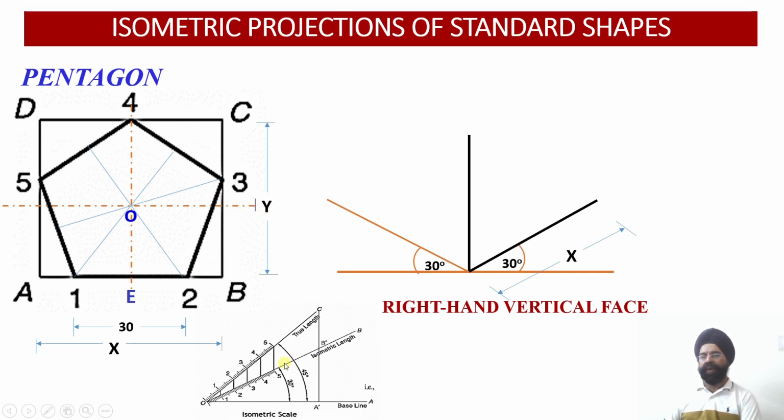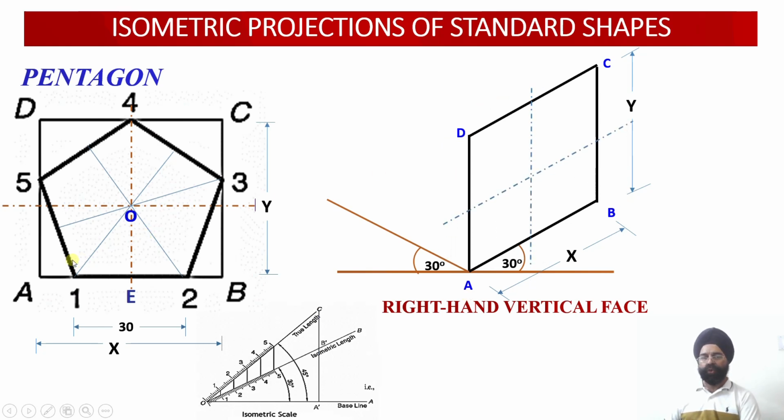dimension of Y. Once you reduce it 18% using the isometric scale. So Y has been located, X has been plotted over here. Just see, this is the vertical length, is length Y corresponding to this construction of the rectangle. So the rectangle construction has been completed, and then you mark all the points. So all the 4 points of the rectangle, they have been appropriately marked, and then using the distance, please check A to E and A to F.